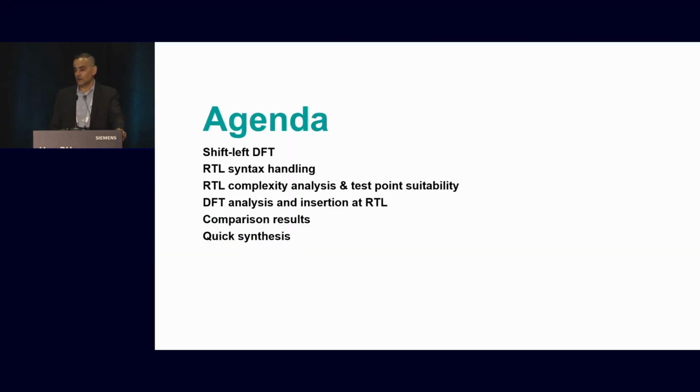Okay, so what I'm going to talk about today is just a few different things. I'll start with a high-level view of the shift-left methodology, and then talk about some of the capabilities that are available to you today. And some of these are pretty new, actually. So I'll talk about high-level syntax handling, the RTL complexity analysis, and suitability for test point insertion that's in the tool. And then go into DFT analysis and insertion at RTL, show you some comparison results, comparing essentially test points at gate level versus RTL and how those results are different. And then I'll wrap up with just a couple of slides on quick synthesis.